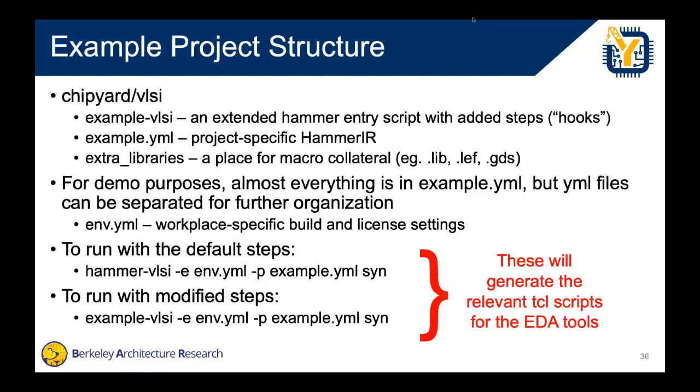Basically, everything's put in example.yml, but you could separate it out into example tools, example tech, example design, whatever. You can add an arbitrary number of YAMLs to your Hammer VLSI invocation. And so then,